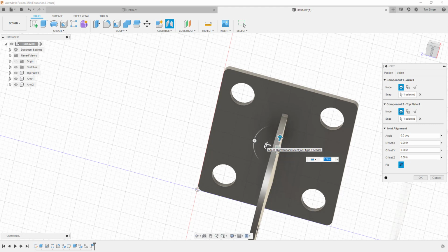We know that the width of the wheel is 3/4 of an inch thick. So I'm going to allow a little bit of spacing between the two vertical arms. So we're going to put 1 inch between those spaces, or 1 inch between those objects. So if I do that for the wheel, then what will happen is I need to move this particular object out. Let's see here. 1 inch minus the quarter. We'll move this out 1 inch.